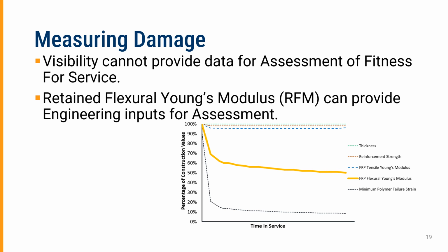Now, these results can be provided by a destructive test, which also means you have to remove a cutout from the material. You need a representative destructive test for any affected zone. It could become very expensive and prohibitive in terms of determining fitness for service. Non-destructive evaluation to detect these changes is what we want to do, and we'll deal with that in the next video.